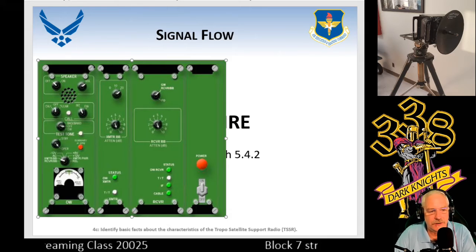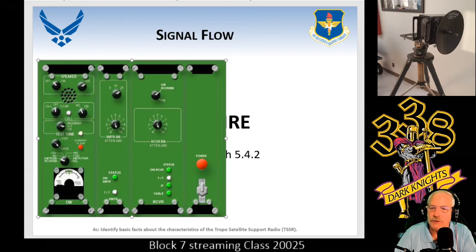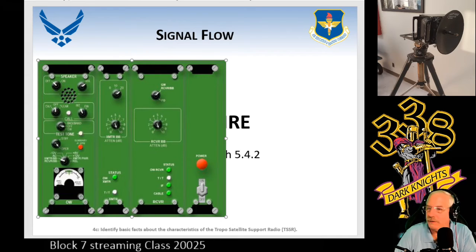You see where the receiver baseband card is? On it you have 2 switches. At the top you'll see GM and FO. This is to switch between the group modem or fiber optics. Again, those are 2 different cables. One has a Canon plug. The other one is 2 BNC connectors on the rear of the baseband assembly. Below it is the attenuator, 0 to 10, only 1 switch.